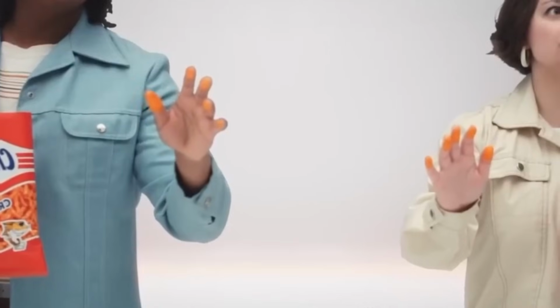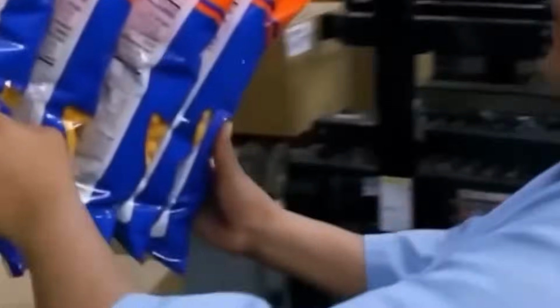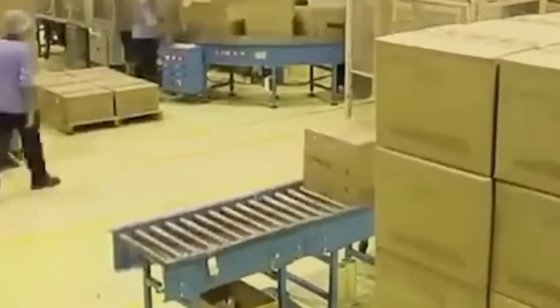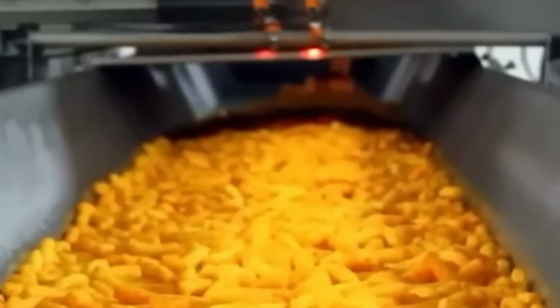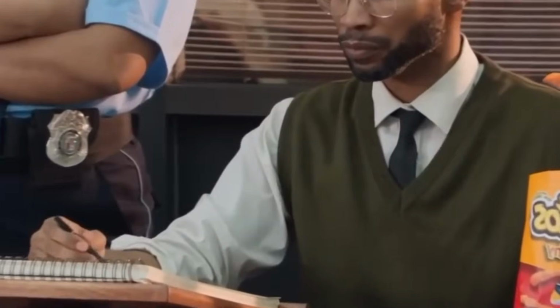Final moisture is targeted at 2 to 3% by weight. After drying or frying, Cheetos pieces are conveyed to the seasoning drum. This is a rotating cylindrical tumbler lined with helical flights to elevate and tumble the product uniformly. The base seasoning is stored in a hopper above the drum and dispensed through a vibratory feeder into a powder